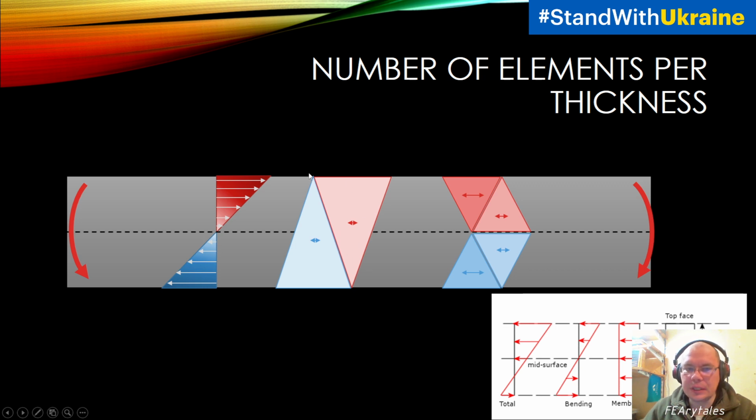And for the reason that we obtain stress in nodes from the mean between all elements, we obtain something like 0 here. Not 0, because here there will be additional elements with tensile, and here additional elements with compression. So here we have smaller tensile and smaller compression, even with these two elements.